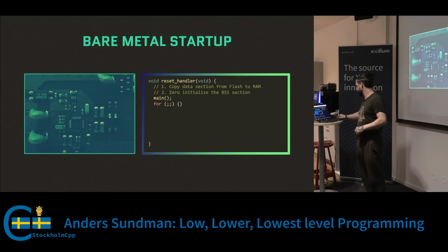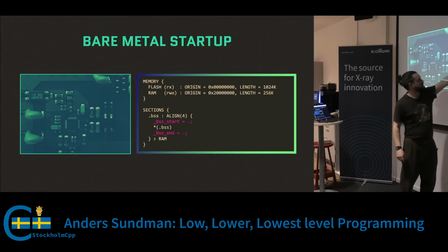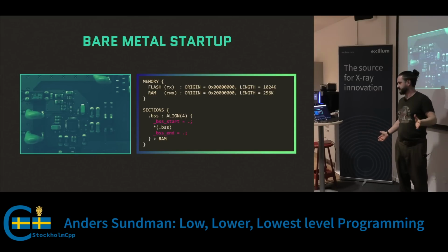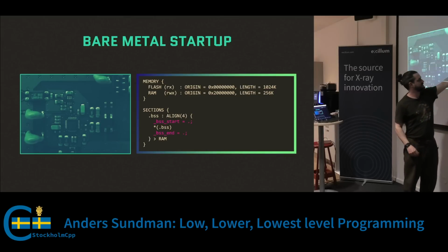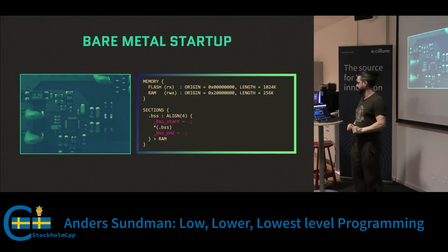So let's behave responsibly and do that. So how do we do that? Back to the linker scripts. When you define the BSS segment, let's start by clearing the BSS segment. When you define the BSS segment, you can introduce symbols that you can then use from your C++ code.